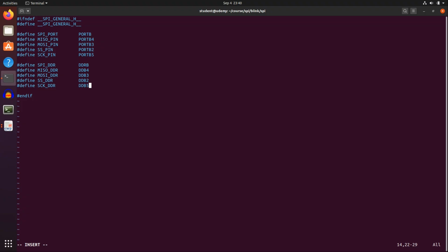SPI is bidirectional. If the master wants to communicate but the slave doesn't have any data to transmit, it has to use a dummy byte that is just sent across. Or if the slave returns some data that the master requested earlier, the master has to clock it, but it doesn't have any data in this case, and hence the master will use the dummy byte. To make sure that in our implementation the value of the dummy byte is all the same, I just define it here. It can be any value that you seem fit. In my case, for instance, I use just an arbitrary value AF in hexadecimal. It can be anything, can be FF or something, whatever you want.